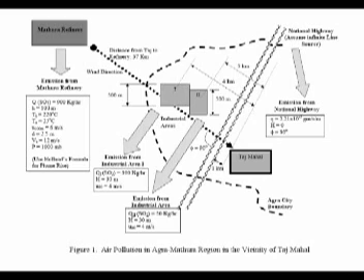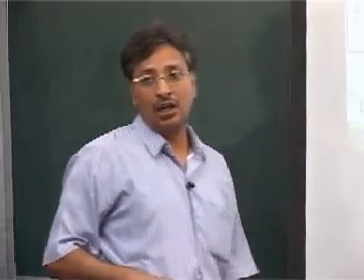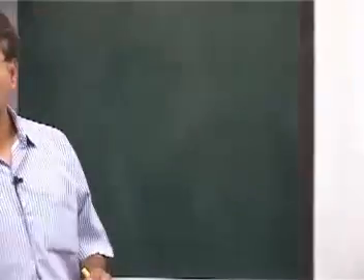SO2 emissions are 900 kg per hour. H is 100 meters. T stack is 220, T ambient is 20. I have already given you the speed at the height of 100 meters. If it was not given to you at 100 meters, you will use u1 by u2 equals z1 by z2 to the power n, where n is a function of stability.